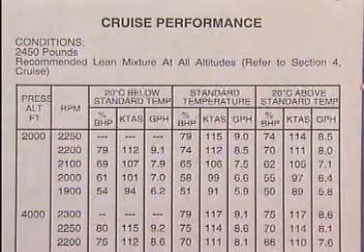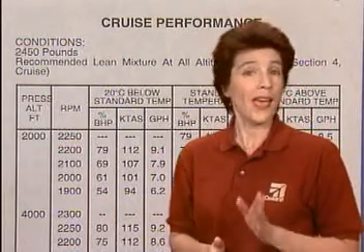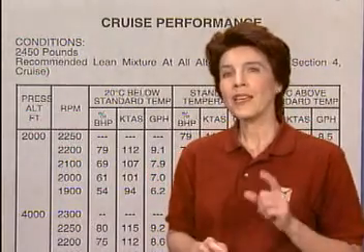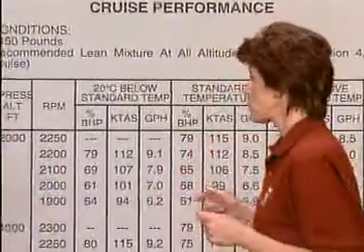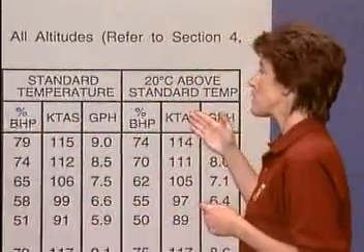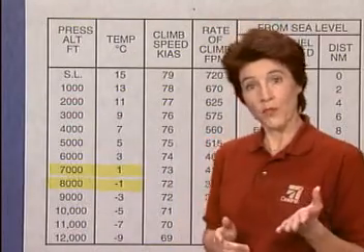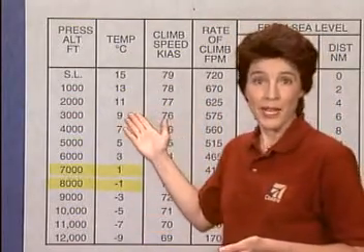Now here's a chart you'll employ when you start flying cross-country. It's called the Cruise Performance Chart, and it's a snap to use, and it doesn't require the computation of either performance benefits or penalties. And while it still has pressure altitudes and temperatures, which scream density altitude at you, it has a different wrinkle that should be immediately obvious. It's the form of the temperature entry. You're given a choice of 20 degrees Celsius below standard temperature, and 20 degrees Celsius above standard temperature. Obviously, you'll need to know what standard is. That's where the standard temperature column in figure 5-7 comes into play, just like we promised you.